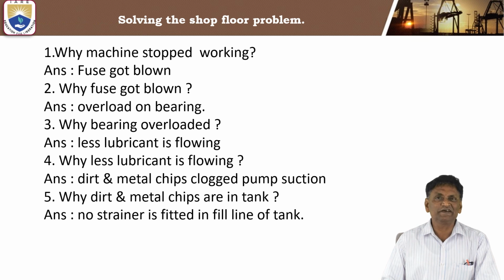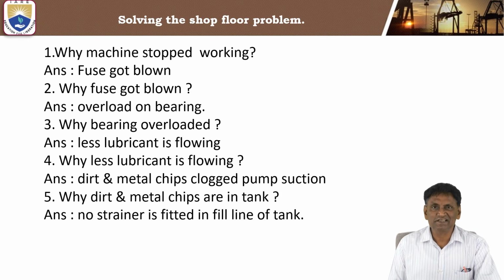If you analyze why there is less lubricant, there is dirt and metal chips which have clogged the pump section. Then why is there dirt and metal chips in the pump? Because there is no strainer fitted in the tank. Like this, they go down to the root cause and eliminate it, and the machine worked successfully. This explains the YY methodology. We can use this methodology for any problem solving.